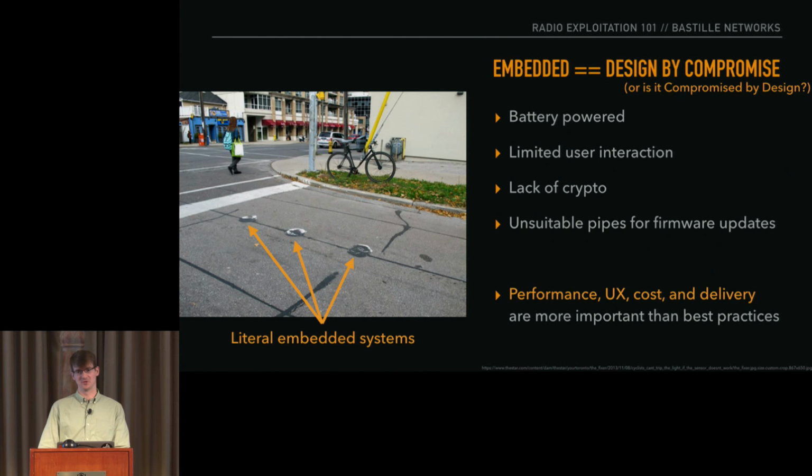It's because embedded systems are really designed to accommodate compromises. Oftentimes you have to develop systems that are cheap, so they can be built in volume. Oftentimes they have to run on battery, which limits the amount of computation you can do on them. Oftentimes they're connected over networks with limited bandwidth, so it can be hard to push firmware to them. Additionally, if they're using one-time programmable memory, they might not even be able to receive software updates at all. So when you look at this, it's not a great situation.